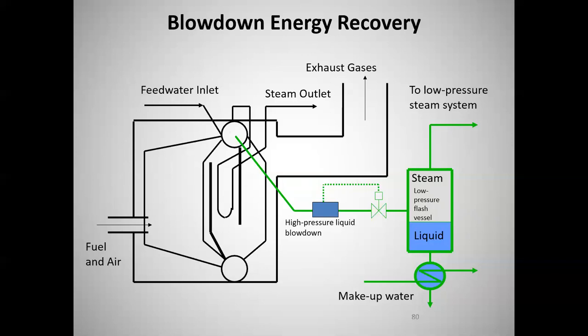And then what you have left is whatever pressure that tank operates at. As soon as that 400 PSIG saturated liquid goes in that tank, the pressure drops and the temperature drops to the saturation temperature at that lower pressure, because you've got both phases present in that tank. If that's a 20 PSIG tank, so 20 plus say 15 for atmosphere, 35 PSIA, the temperature of that liquid would be the saturation temperature at 35 PSIA out of the steam tables. That's still going to be 240, 250, 260, 270, something like that.